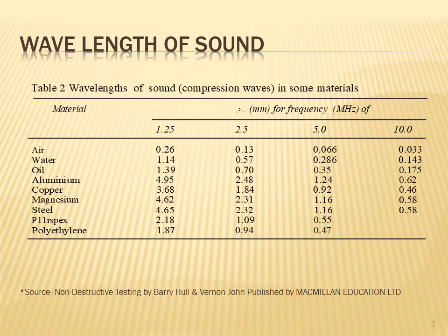If we talk about defects, for example, we take steel. In case of steel, when we want to find the minor defects, we require a high frequency. And vice versa, when we want to find larger defects, we require a low frequency.